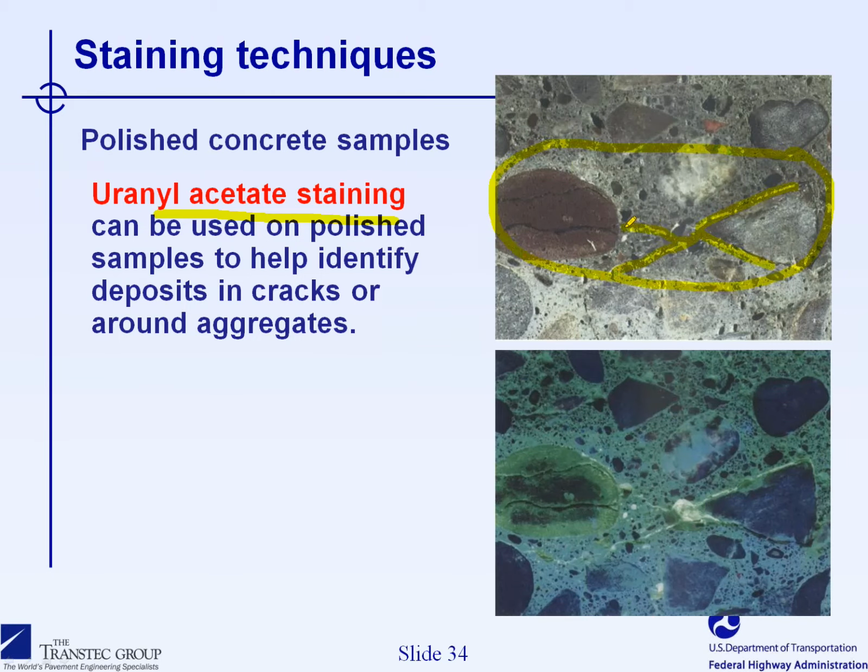Here you see the reaction products in the cement paste. And when you apply this uranyl acetate solution at the surface of the affected concrete, there will be an ion exchange process between the alkalis present in the gel and the uranyl acetate from the solution.